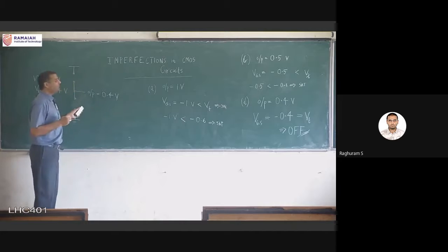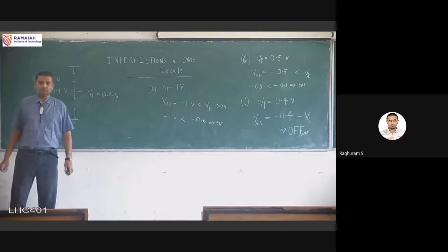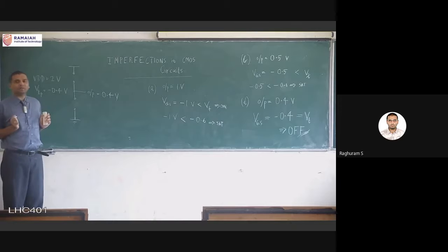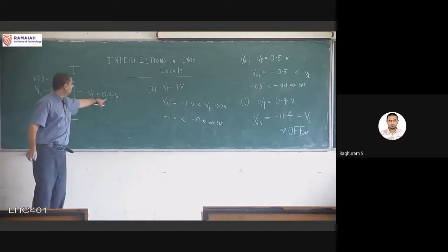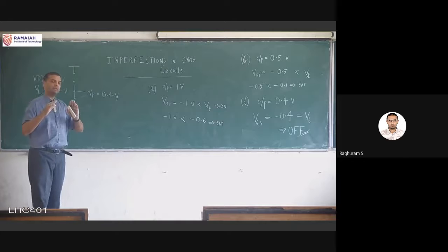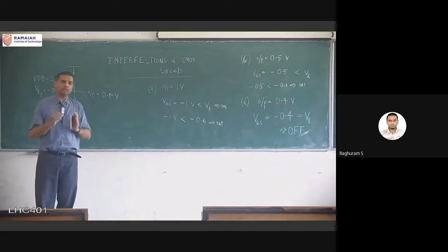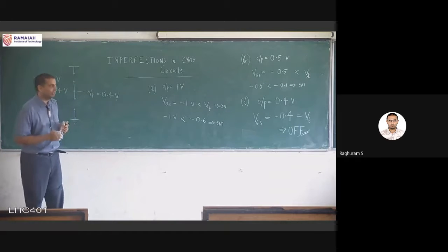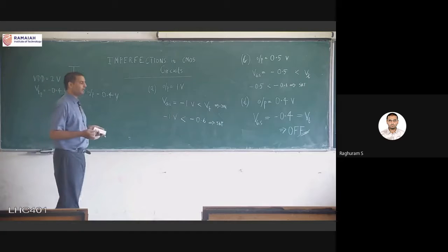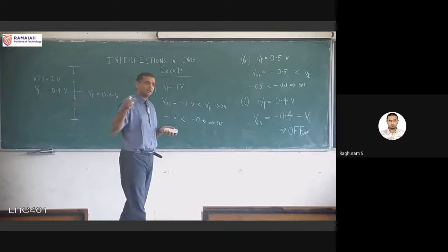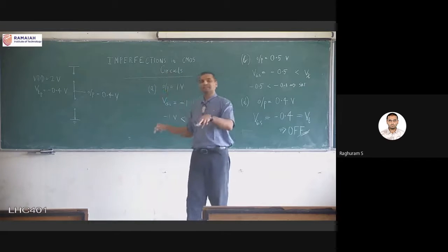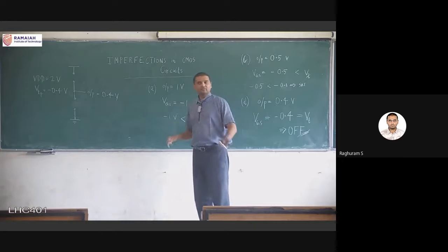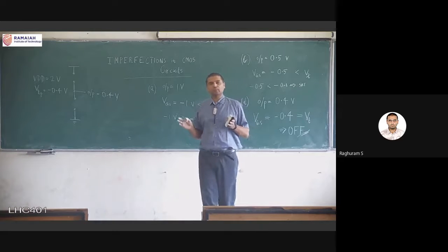this will be our equivalent circuit. The transistor will stop conducting. When it stops conducting, current cannot flow, the top part is still not conducting, and this will be the final value of the output voltage. It cannot go all the way down to 0, because like I said, it's not an imperfection of the transistor, it's an imperfection of the circuit if you connect it in this way. It's a defect that the designer has created, not the transistor itself. The transistor is still following its own properties.